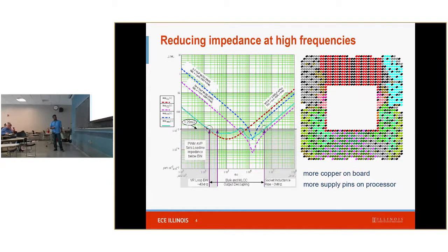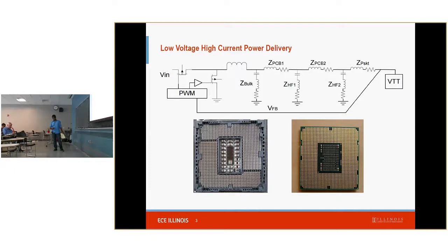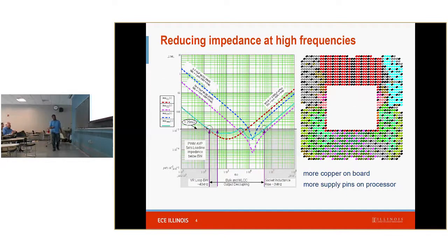I have my bulk capacitor impedance over here, which is the red line, and then there's the magenta line, which is my ceramic capacitors, and then I have my third stage, which is the blue line, and overall effectively it should follow something like the minimum of these curves, or it's a bit more complicated than that, but there's going to be a zero over here, and so that's what we see.